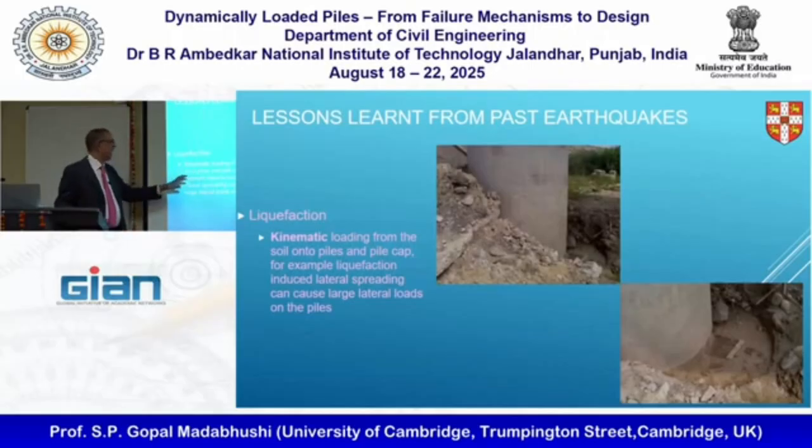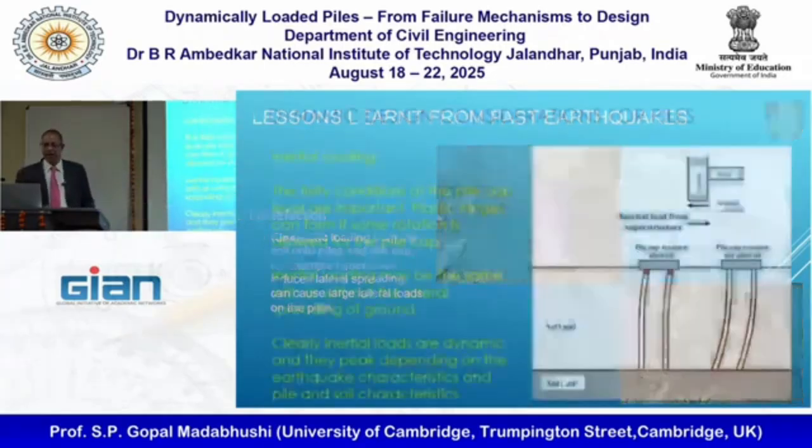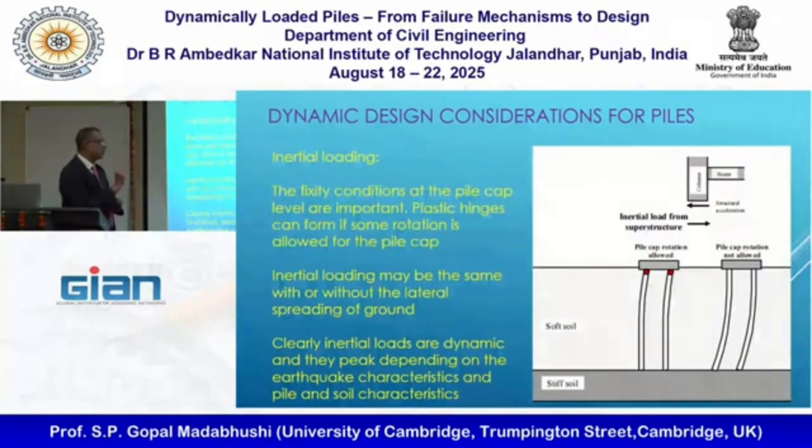And that is all actually kinematic load coming onto the piers and the piles below because the soil wanted to go walking and you stopped it. It doesn't like that at all. So, this is all coming because of the movement of the soil. Therefore, we should call it the kinematic loading. I'm not the first one to talk about inertial and kinematic loading. This has been going on for some time. And let's see where we are.